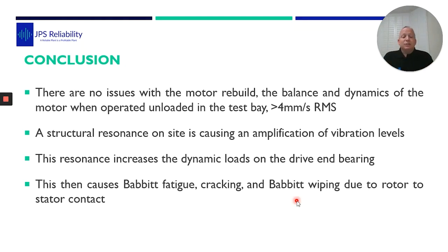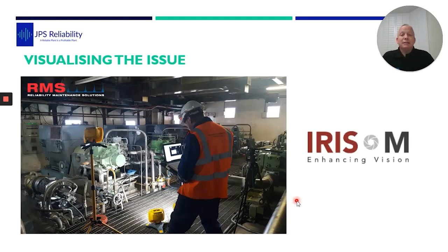And at this time, I was chatting to Keith, RMS, and they were using motion amplification. So this has just come in and they're starting to use it and find their feet with it. So I gave Dean a call, got all the stuff in and Keith. Keith came down to site, and with Keith we tested the motor. So I had all my bump test data, all my vibration data. I knew that that motor was twisted. I knew the frequencies it was running at.